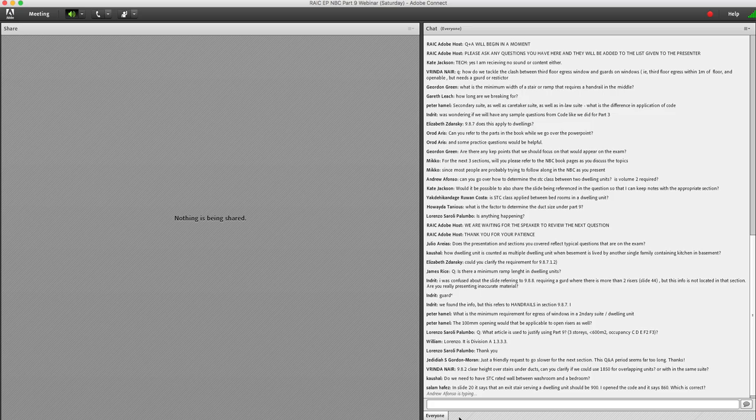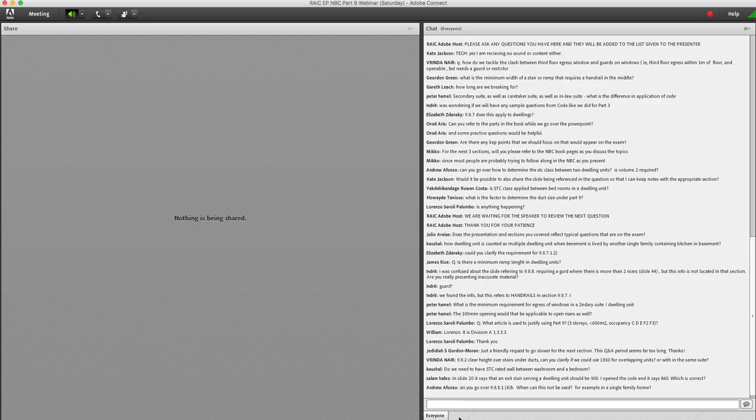For the duct, there are equivalent duct flows within 9.32.3.11, depending on the airflow in that duct. There are some sizing diameters, but it's all related back to your fan sizing. It's more of a question you might want to talk to a mechanical engineer about. For example, table 9.32.3.11A talks about fan external pressure, so it relates back to how you're designing your entire system and depends on the length of your duct.